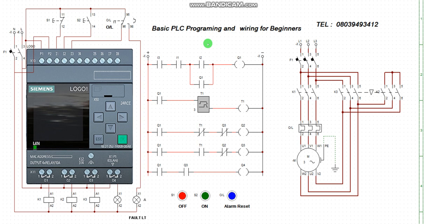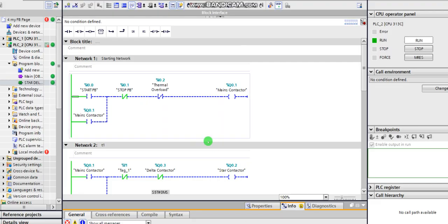And in some cases, you may not even have to do the connection to PLC directly. You may also have to interface a relay between the PLC CPU and your panel. Okay, there are some connections that will require you to feed a relay between this and your field device. All right, that's what I mean. So now I just want to show you the process of terminating your PLC wiring. This particular software, let me show you.